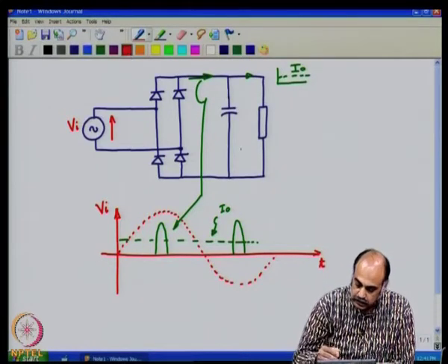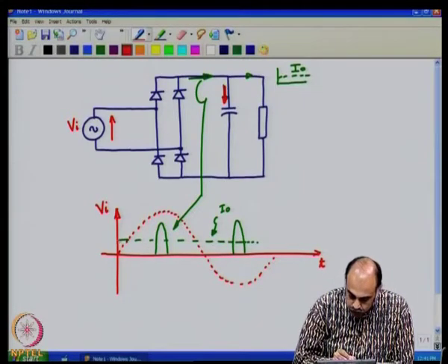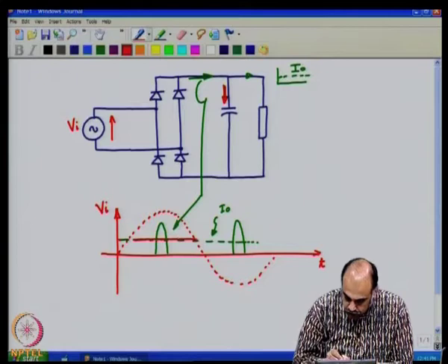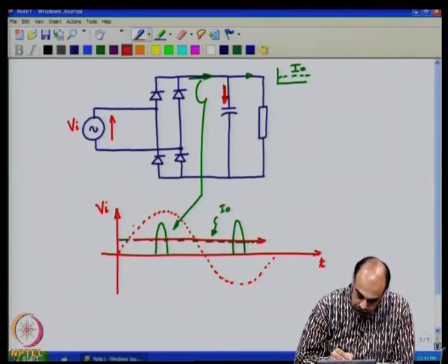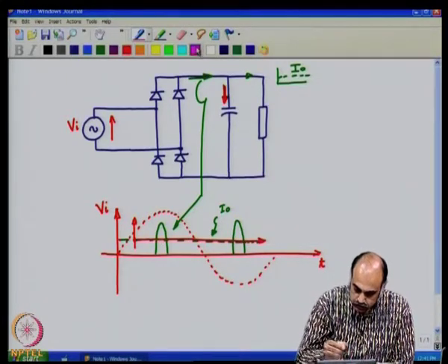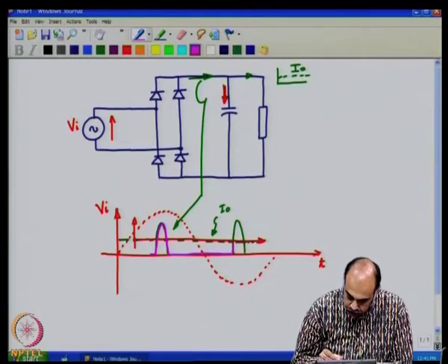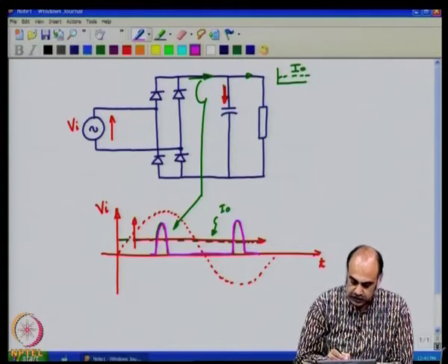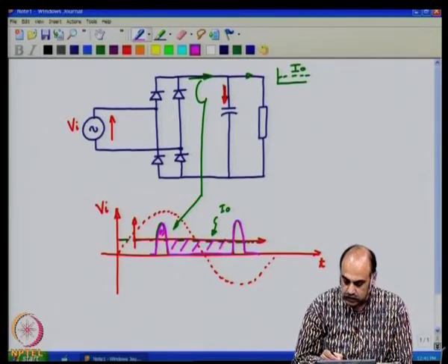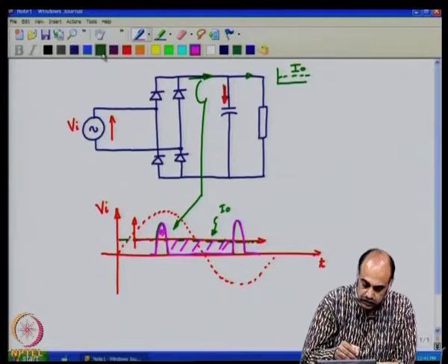Then the capacitance current, the red arrowed current, would have a 0 based on this, something like that. You will see that it goes in this fashion. The essential idea is that the charge here gets cancelled with the charge here, and it is a pure AC current that is flowing through the capacitance.